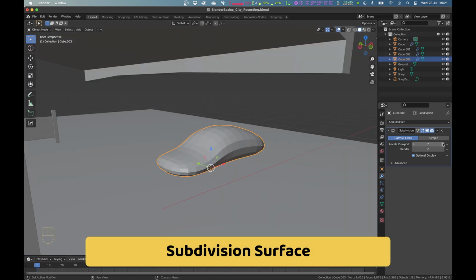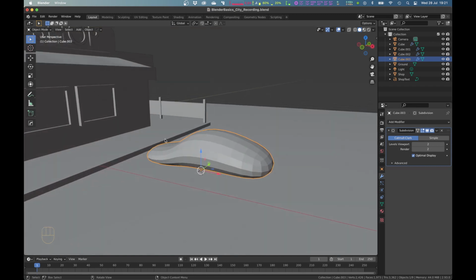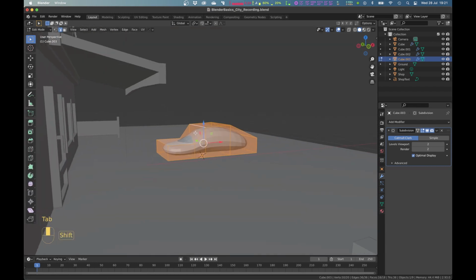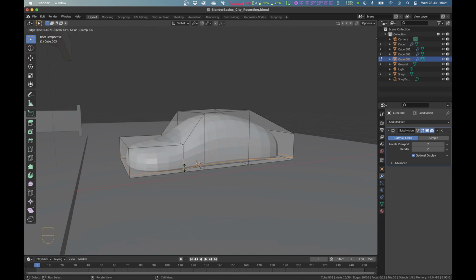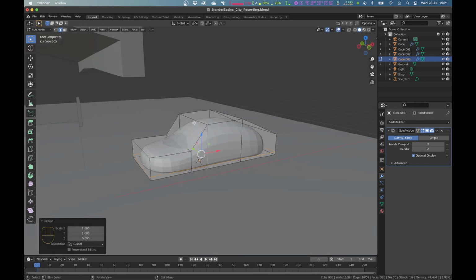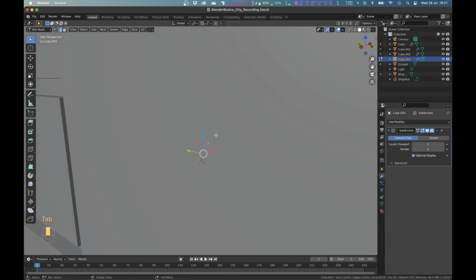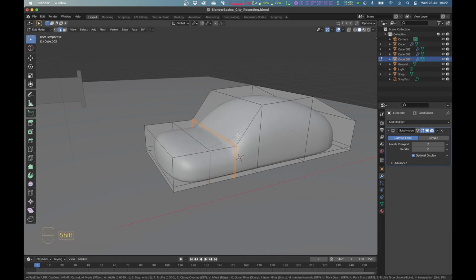What is awesome is that modifiers are non-destructive. The mesh is still this ugly cube. The modifier splits faces into smaller faces to make it smoother. Now in edit mode we can add a few more loop cuts or bevels to kind of sharpen some edges and corners. Like that, for example. I will scale this new loop cut on the Z axis and type 0 to straighten it. We also want to add a shade smooth. Alt click to do a loop selection, and you can bevel some edges with Ctrl or Command B.